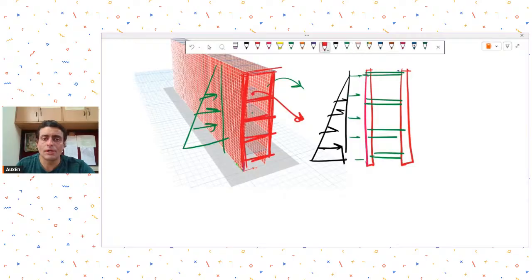It will just become a frame subjected to lateral loads. If you want, you may think of adding bracings also if required. If you're sure that the lateral load is going to be in one direction, you may add bracings like this so that they are in tension and your reinforcements can take those tensions. So this slab that you have provided and this back wall that you have provided, I don't think they are helping you, and they are just inefficient.